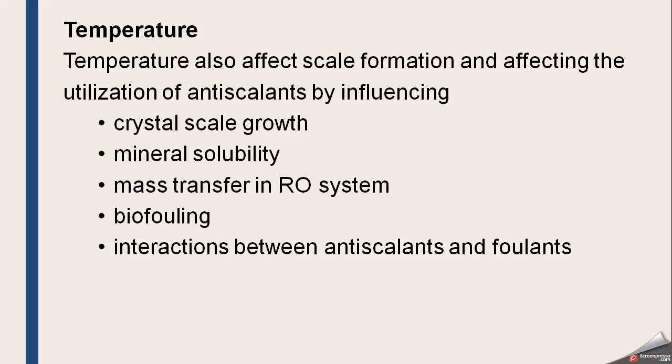So there must be a reasonable distance in the addition of both of these things. And third is temperature. Temperature also affects scale formation and the utilization of antiscalant, because temperature affects the scale crystal growth, mineral solubility, mass transfer in the RO system, biofouling, and also plays a role in the interaction between antiscalant and foulants.